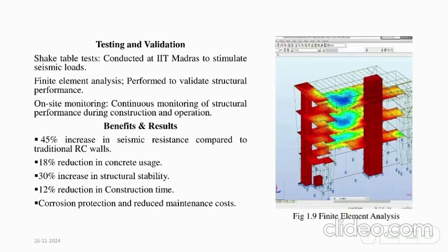The BMRCL underwent rigorous testing, including shake table tests conducted at IIT Madras to simulate seismic loads, finite element analysis performed to validate structural performance, and on-site monitoring of structural performance during construction and operation.